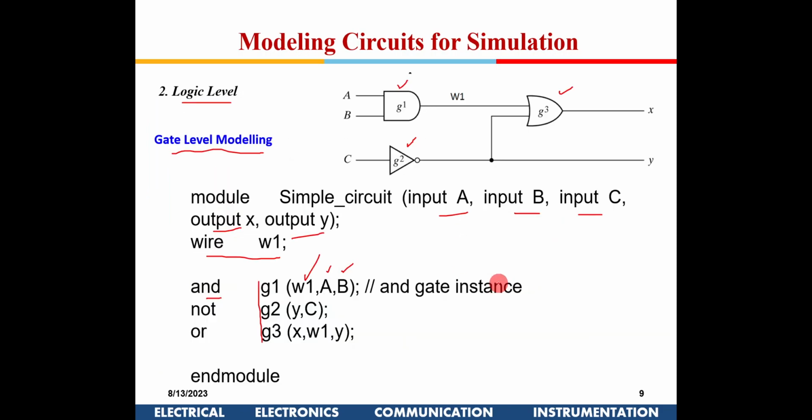But when you are doing gate level modeling, you are picking the gates yourself. Here the only optimization you can do is set goals for power and so on. If your goal is power, then in the library there could be a low power AND or a fast, high power AND, so it might pick up those gates.